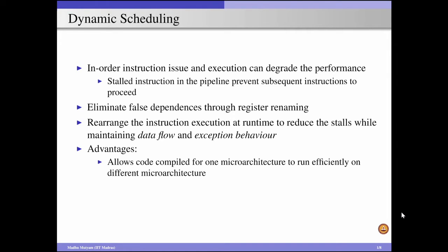For example, AMD processors and Intel processors can use the same ISA, x86, but the way the processor is designed in AMD can be completely different from the way the processor is designed by Intel. A single ISA can be realized through multiple implementations, and each implementation corresponds to one microarchitecture, so we can have multiple microarchitectures which have the same underlying ISA.